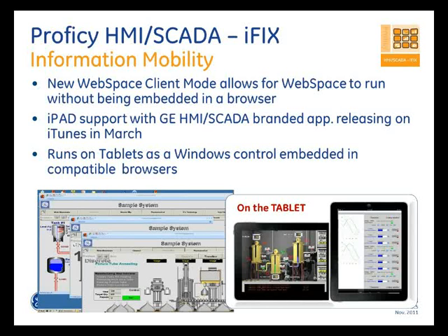In a couple of weeks, we'll have a Prophecy SCADA app on iTunes. When you go to iTunes and search for Prophecy SCADA, it will come up with an app that you can download on your iPad and connect to the WebSpace server. The app is at no cost on iTunes. It basically consumes a CAL that you will have on the WebSpace server. So again, since WebSpace works in a concurrent licensing environment, if you use that CAL to run an iPad client, obviously you'll have one less client that you will be running somewhere else. But that's more of how you manage your concurrent client connections.